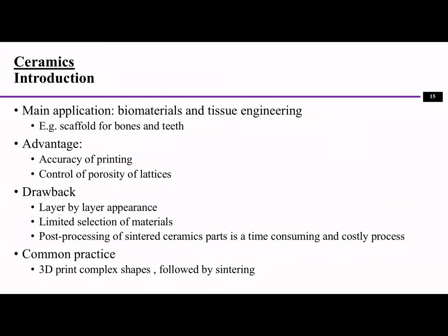And also post processing is required because we have to sinter the internal structures of the part, and it's a time consuming and costly process. So the common practice is we create the shape with 3D printing, and then we use sintering or firing to bond the materials.